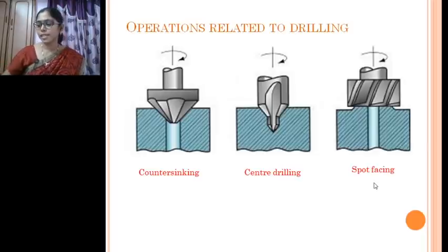For example, if I have a cylindrical rod like this, and I need to center it, the center drill produces a small depression at the center point so the workpiece can be held at that particular point.